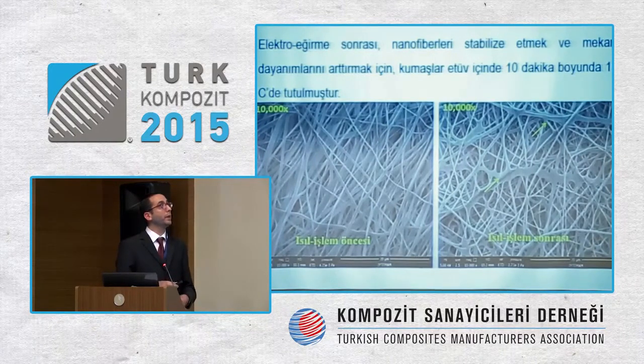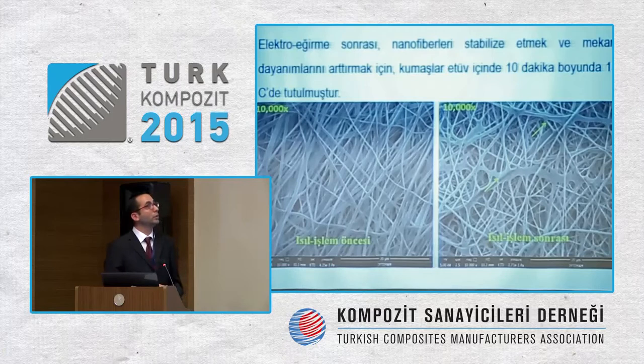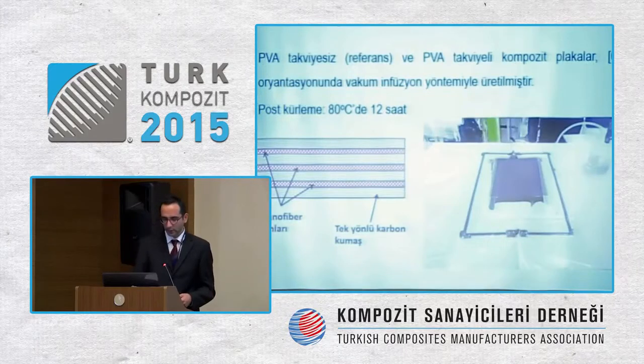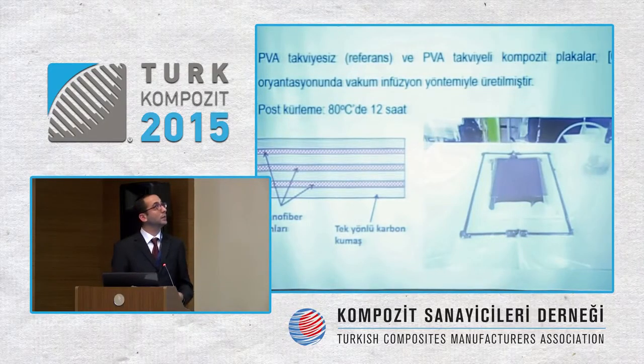And in line with the literature, in the post-electrospinning period, to increase the stability and the mechanical resistance of the fibers, we kept them waiting for 10 minutes in 150 C. And you can see that they are connected to each other as webs, and we can see it more clearly in the right-hand side picture.